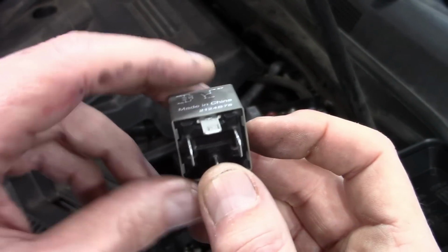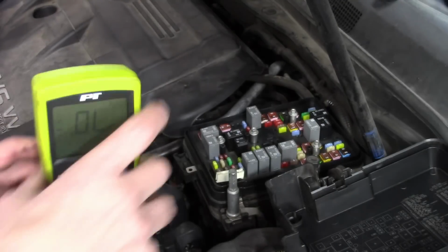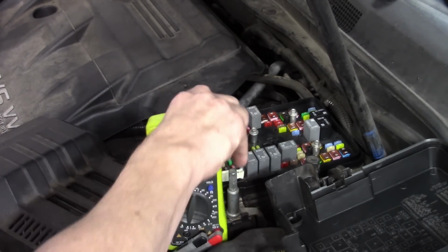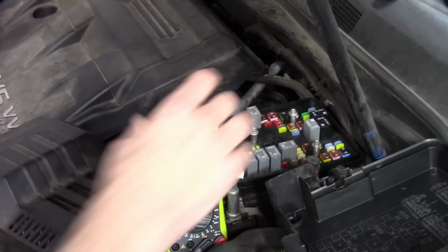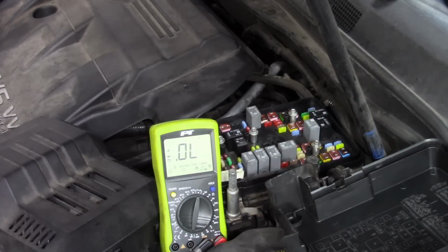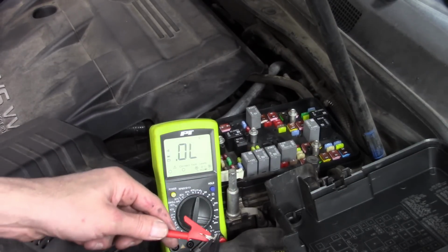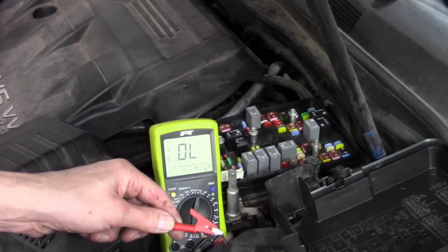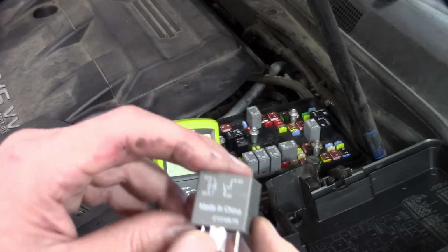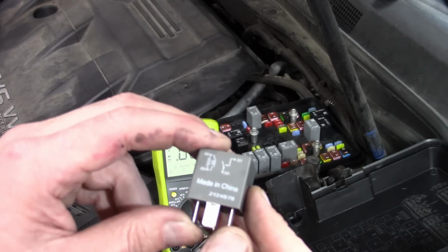All right, now we can use a DVOM as well to check this. If we go to the diode mode, we should detect any kind of continuity regardless of our resistance, pretty much, so we're going to go there. The other thing I like about it is we're going to have an audible signal. If we have continuity in a circuit, the meter is going to beep. We could actually do this without a map, but we have the map, so we have a little bit easier time.